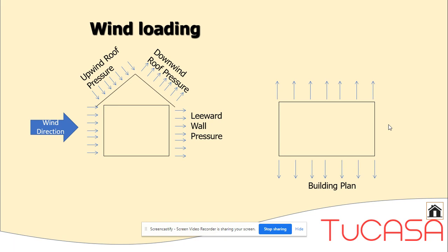Make sure that nothing moves too much, and we've got a stable structure. This stability is achieved through the cellular interconnection of external walls, internal walls and partitions, and even the chimney acting as a pier as well, combined with the roof structure.